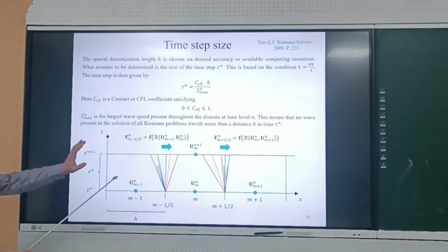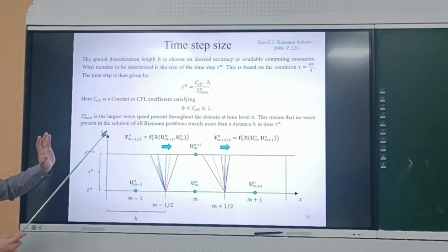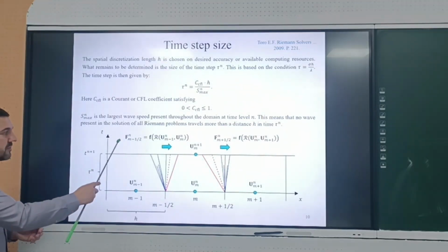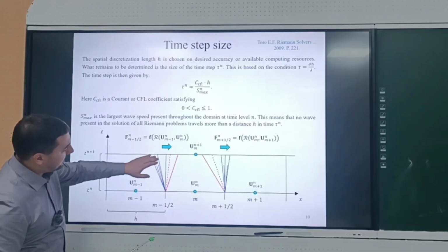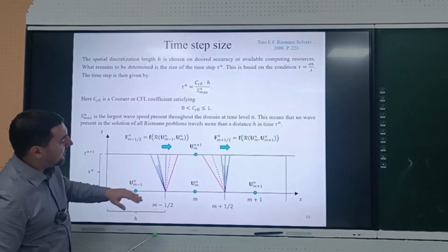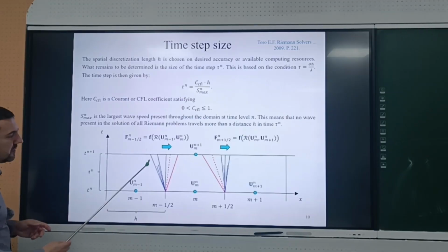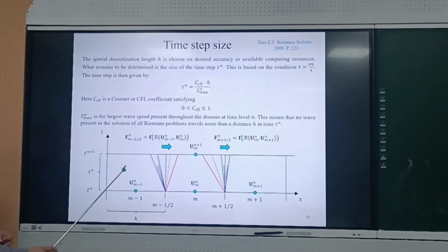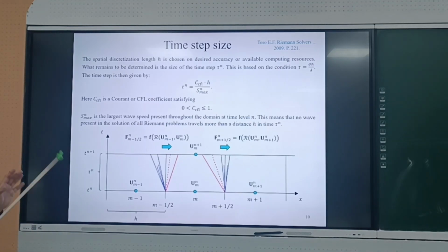So this is the sketch corresponding to the Godunov solver. In the Godunov solver, we have information about all these waves. We do not actually use them. To compute the numerical flux, we need only parameters in the necessary region in our solution. We do not need to compute the waves or the speed of this shock wave or the parameters of the characteristics of the expansion fan. But nevertheless, we can get this information if we use the Godunov method.